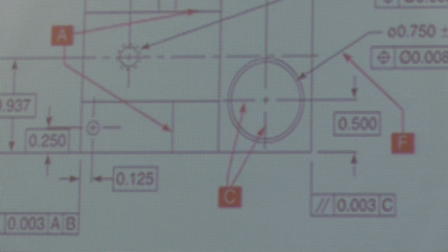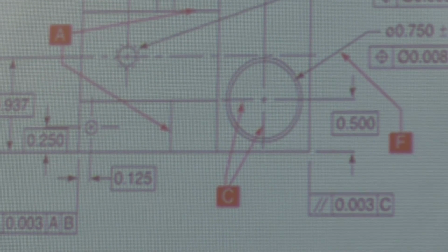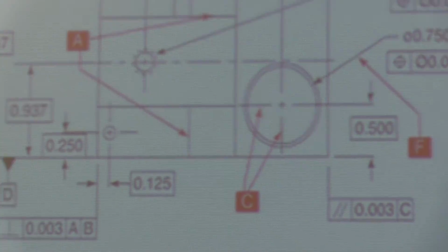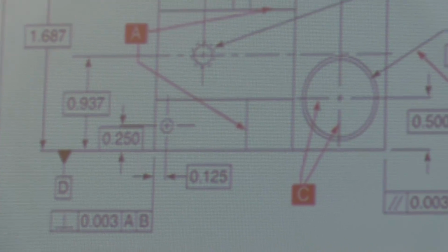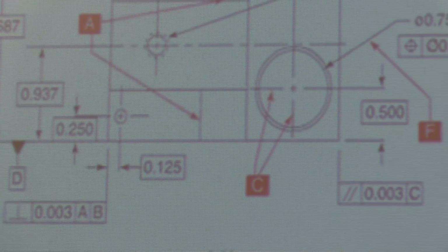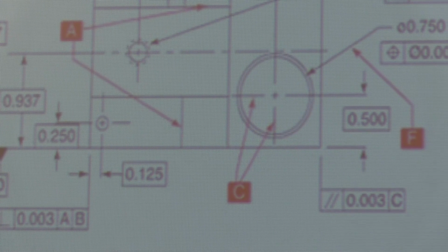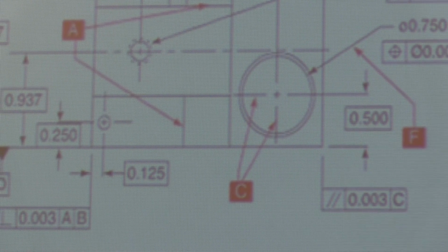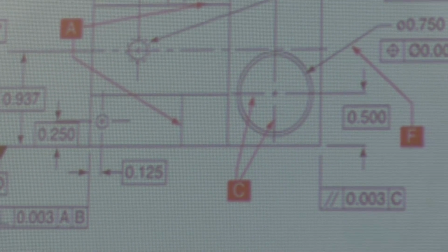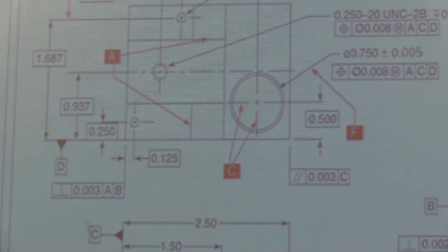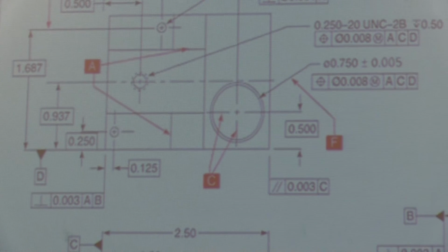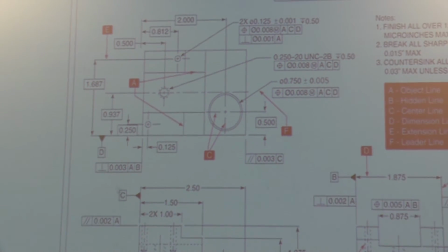So what you're saying, Dan, is that it's easy, you should always work from one edge, right? Correct. I like to work from the datum line. Wherever the engineer is set up his datum line, I'm going to follow the same path that he drew it in. Okay. So in this print here on the top view, how do we know where the datum line is?